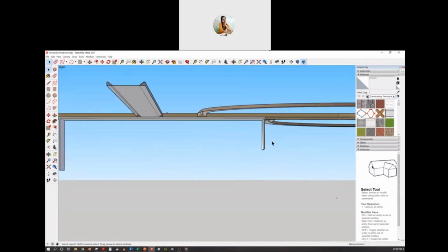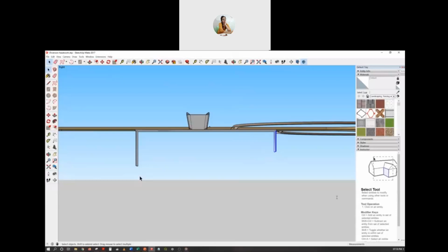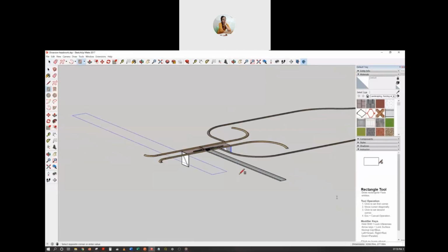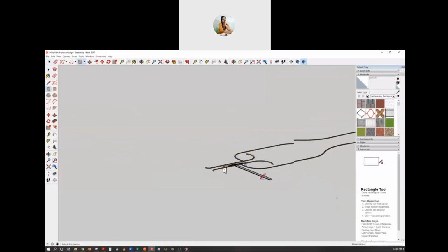So now you can see water has to enter like this, then it will go like this, then it will flow horizontally, then again it will come back like this, and it will be released at the end of this impervious floor here. So we have vastly increased the length of travel of this seepage water. That means its velocity will be reduced, and therefore the rate of seepage will also be reduced. So this is how we can understand the different components of this diversion headwork.